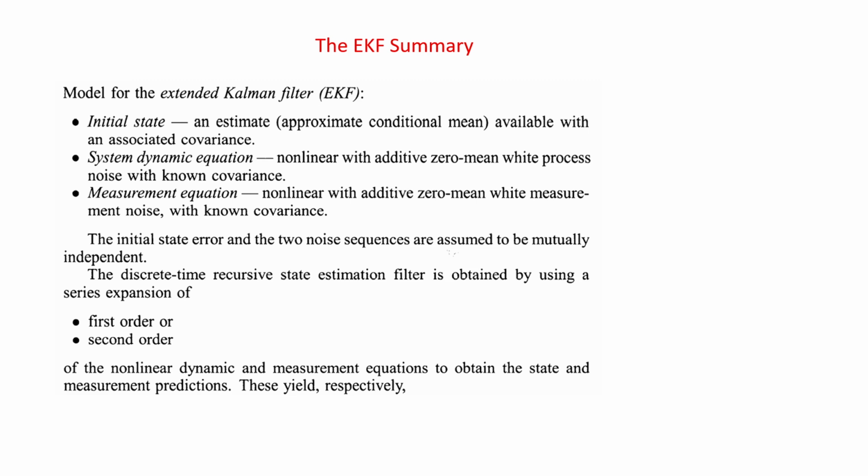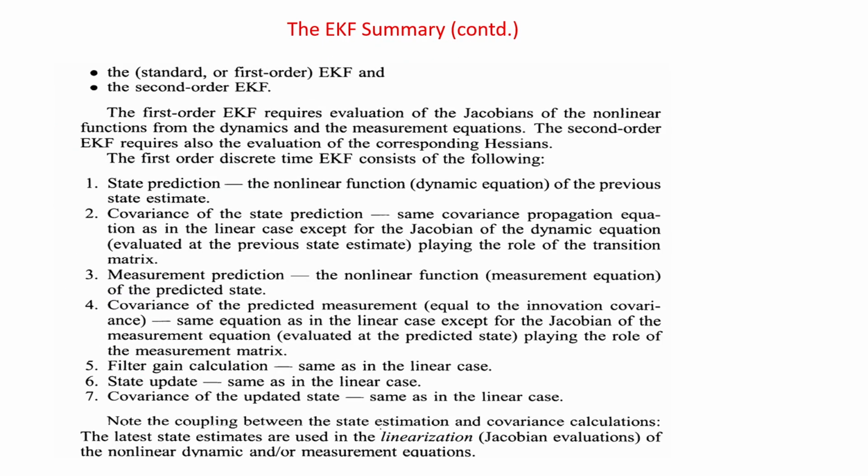So, you start with your initial state, which is your Kalman filter initialization, same as Kalman filter, system dynamics equation, measurement equation, these are all fine. Here we talk only about first order because we have not done second order. So, first order only EKF we have studied. With the first order EKF, you now have two cycles, one is your prediction cycle, one is your measurement cycle or estimation cycle.